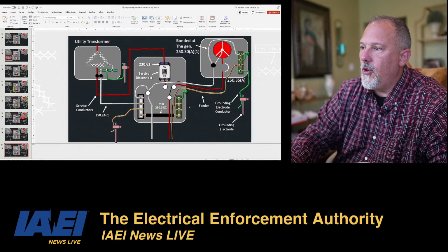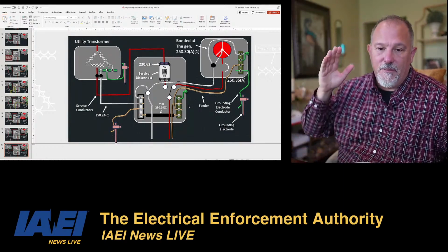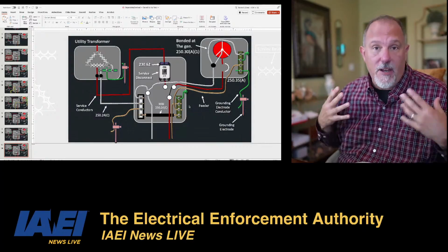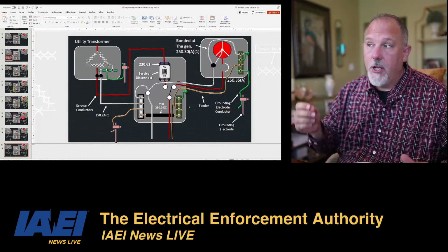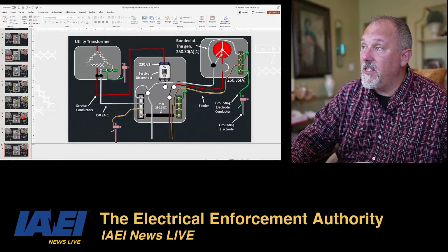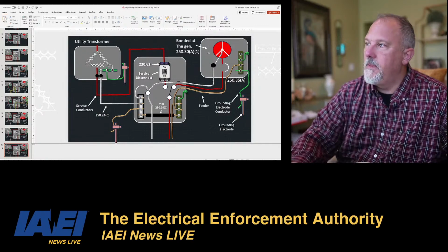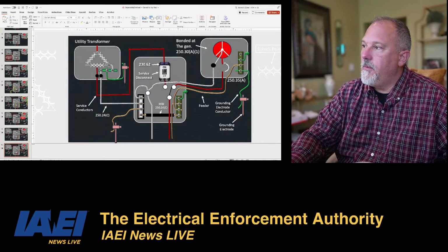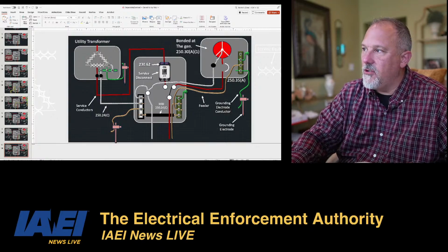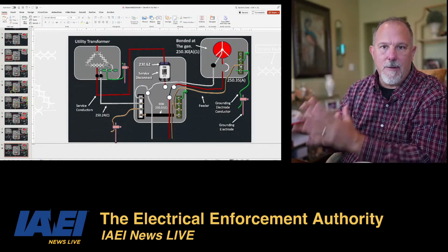So you have a choice, right? You could say, look, what you need to do is buy a new transfer switch. You need to go buy a 4-pole transfer switch. And I would say, no, you don't have to buy a 4-pole transfer switch. You don't have to replace the transfer switch. All you need to do is go into the generator and do this. Delete. You delete the connection between the grounded conductor, this neutral conductor, and that ground bar. And now it's a non-separately derived system.